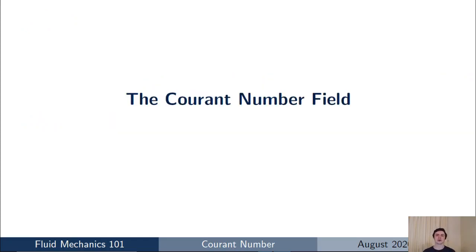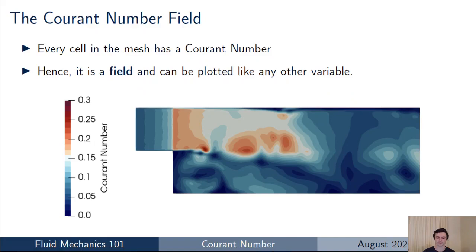So what I want to move on and talk about now is the Courant number in a bit more detail and reveal a few things which you may not have fully understood and will really help you to understand the Courant number when you apply it to your own CFD simulations. And the first point I want to make is the Courant number as a field.